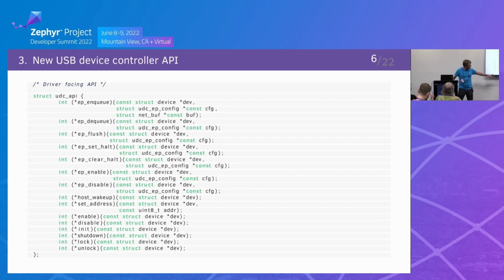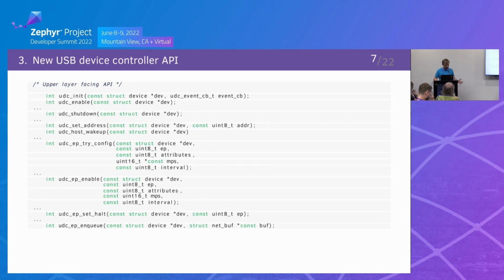So the driver has to initialize a table with its endpoint configurations, and then the common layer transfers that depends on metadata too. The same goes for the synchronous calls like endpoint halt or halt clear. So that puts the endpoint in the state to reply with a stall handshake.